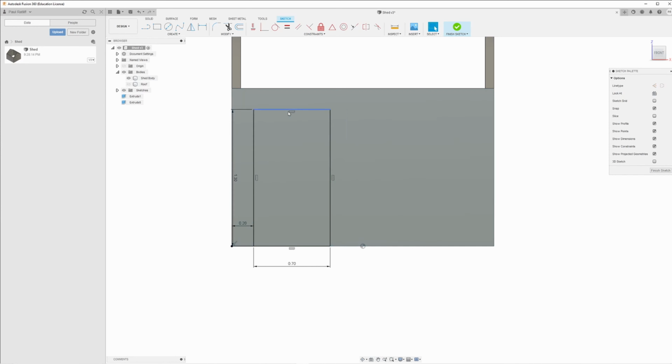Okay, now here is our entry door area. First thing I'm going to do is get rid of this little registration line. We don't need that anymore. Apparently had two there. Okay. Now again, we want to make a casing around the door, correct? So what we're going to use again is the offsets.